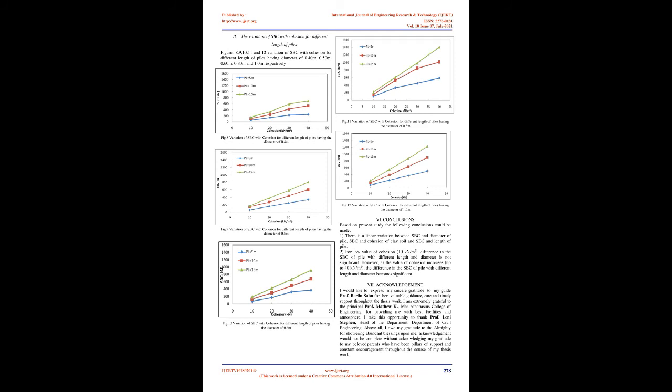It may be observed from tables 4.2 to 4.4 that, in all the cases considered, the criterion of 2/3 times load corresponding to 12 mm is critical when compared with the criterion of 50% of load corresponding to deformation equivalent to 10% of pile diameter.